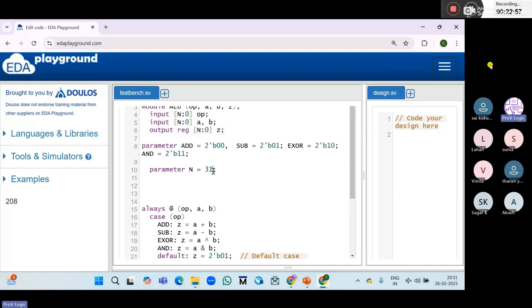Instead of changing there, if you change directly here to n, this n value will be substituted, so directly it will be 128 down to 0, or 127 down to 0, or 63 down to 0. Based on your n value, it will be allocated the same. It's a constant.